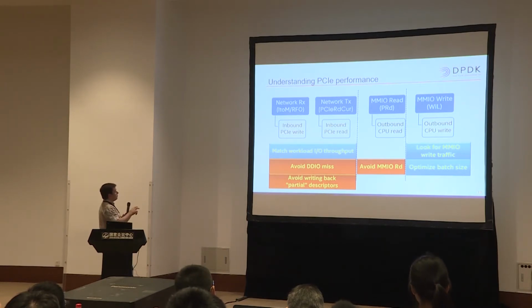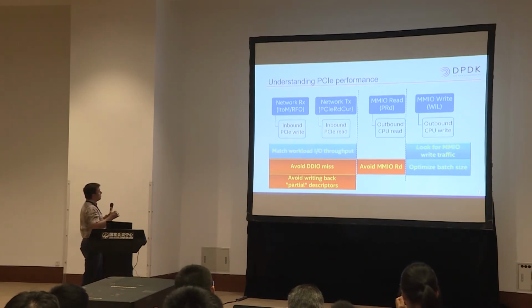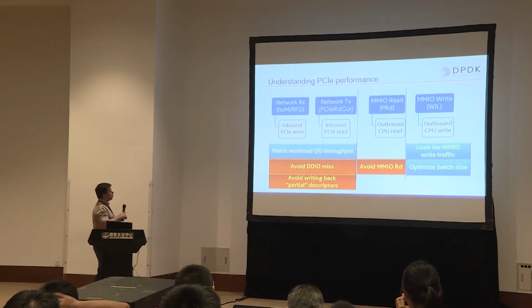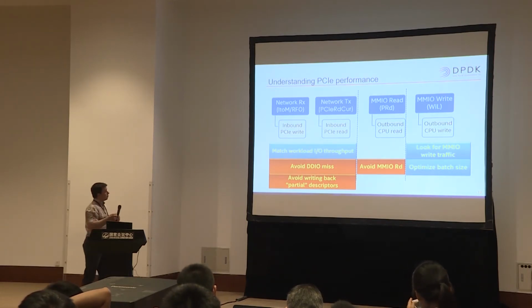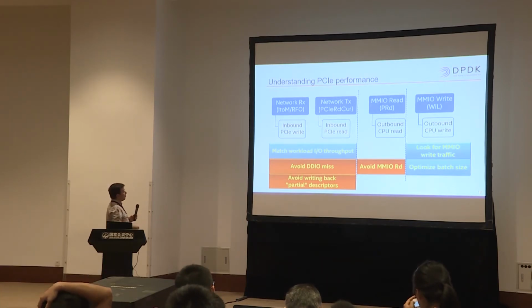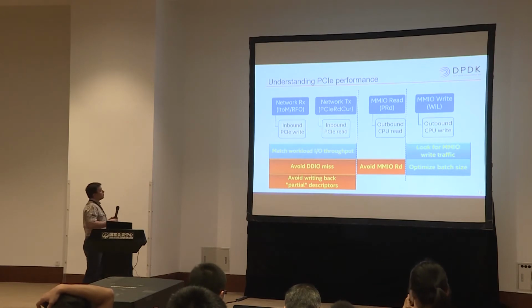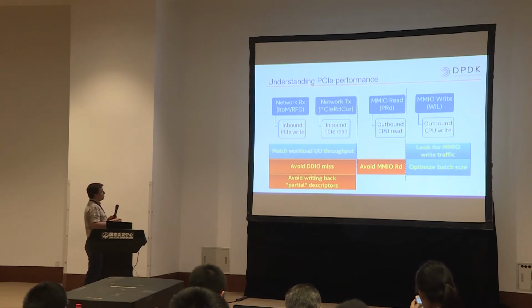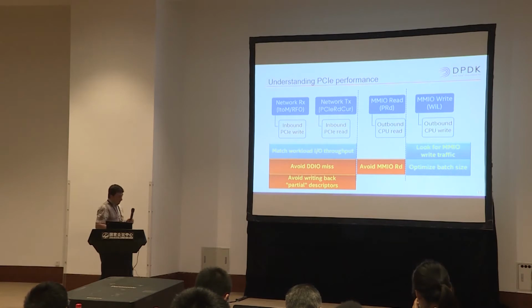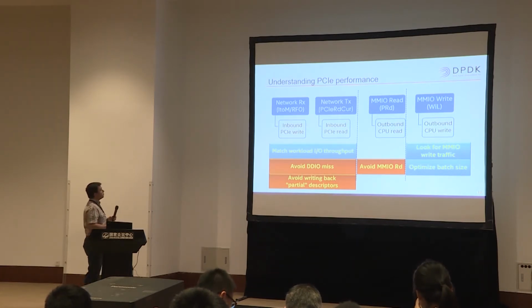We can divide flows into two directions: inbound, that is flow from the I/O device towards the CPU core, and outbound, when the CPU core writes or reads something from the I/O device. We have dedicated counters to track each transaction, and it's also worth mentioning that for inbound writes, we have counters to track both 64-byte line and partial writes. So it's I/O and 4 counters we have.